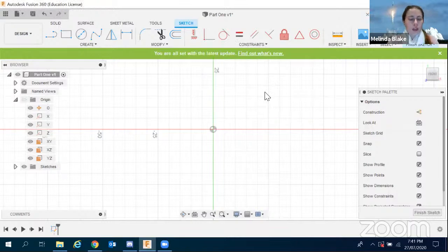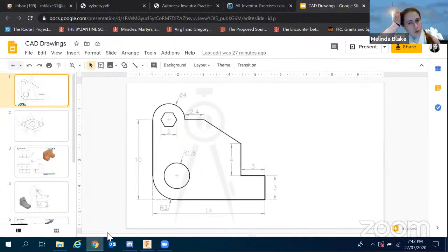So the first thing when it comes to creating a sketch in any CAD program is to figure out which part of the sketch you want to lie on the origin. And that's actually a really important decision in parts that have some kind of symmetry, a little bit less important if, like in the part that we're doing now, there really isn't any symmetry at all. So if I just go back over momentarily, I think what's going to make sense for me tonight is if I place the origin of my plane down here in this bottom left corner, and I'm going to place everything in this sketch up in the first quadrant.